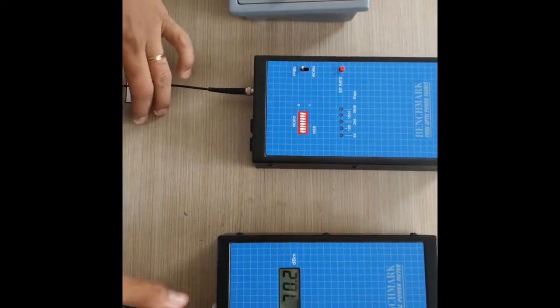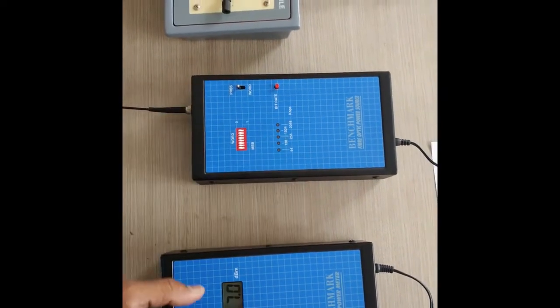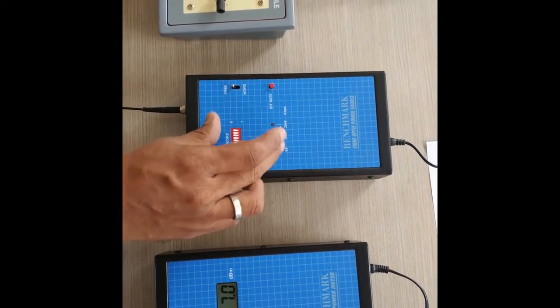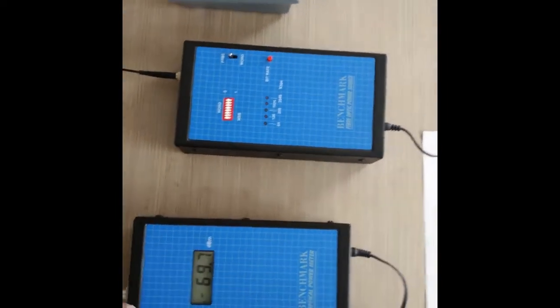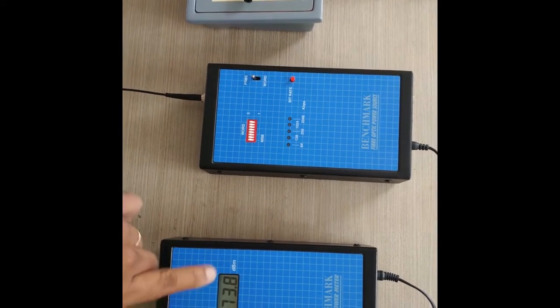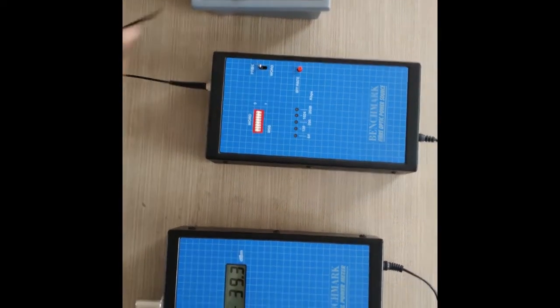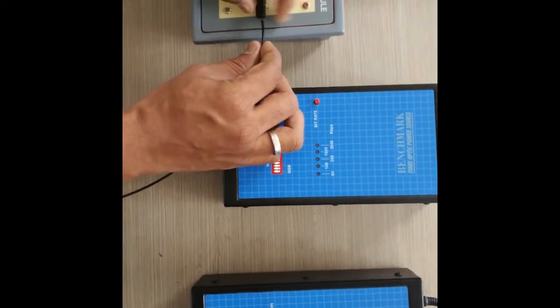This optical fiber is connected to a power meter in order to measure the output power, that is, the power generated from this optical source. We are measuring using a power meter. We have here around minus 60 to minus 70 dBm of power, and I am going to feed this optical fiber, connecting the optical fiber to this kit.